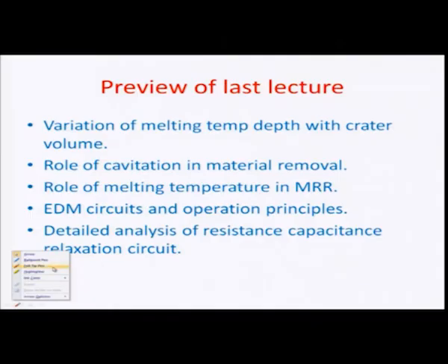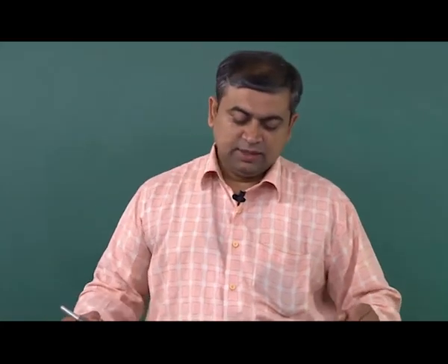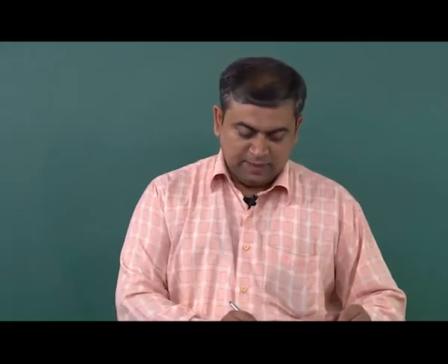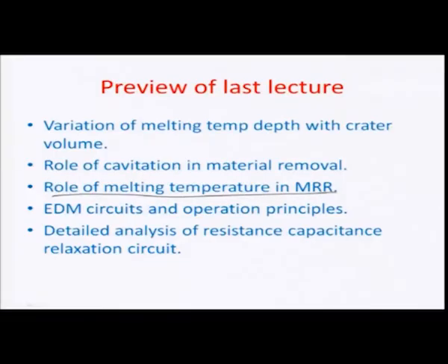the role of cavitation in material removal, particularly because of the formation of plasma within the EDM. There is a tendency of a low pressure region to be created, which actually drives away most of the material and is responsible for most of the material removal in the EDM process. We also considered the role of melting temperature in the MRR, material removal rate, and then we discussed some basic